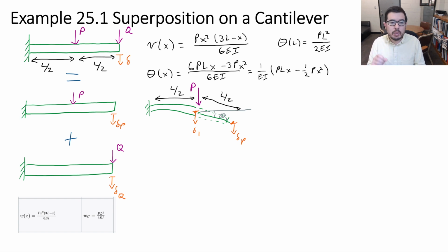But unlike some of the problems that we've discussed, like with axial loading, when you have a region that's got no internal normal or axial force in it, and it's along for the ride, it just shifts to the right, shifts to the left, or goes up or goes down. We still have, at this location, a slope. So if we model this as being at the end of a cantilever beam, that's fine. Delta 1 is going to follow this equation at this point, but we have not a length of L, but a length of L over 2.